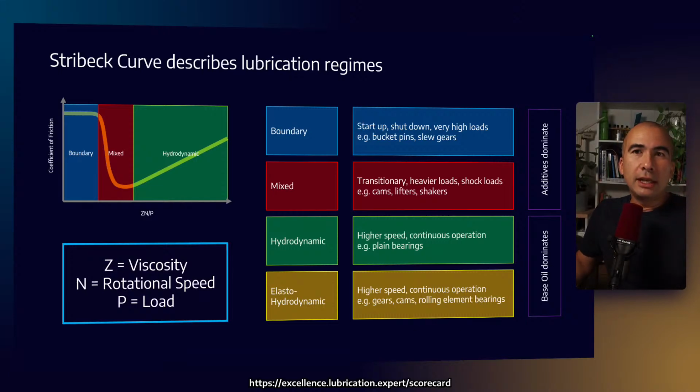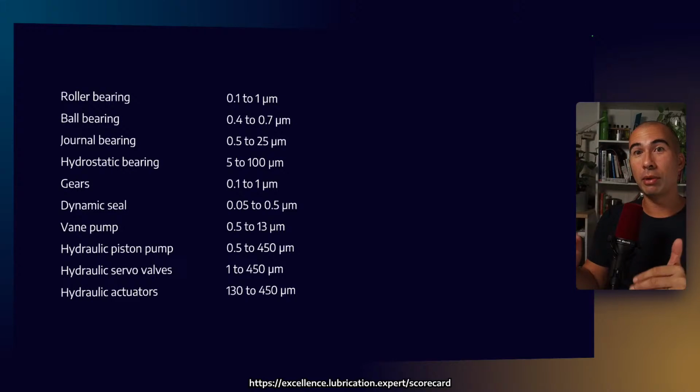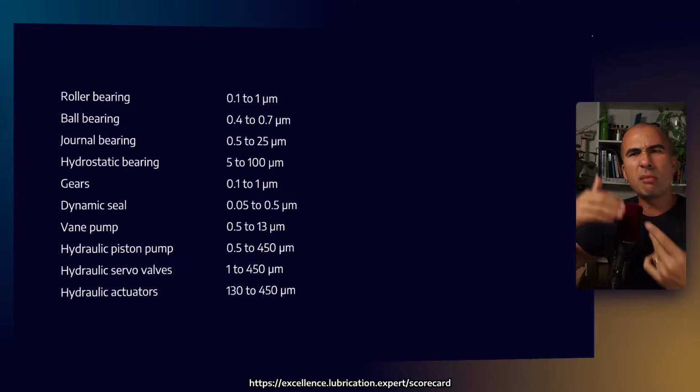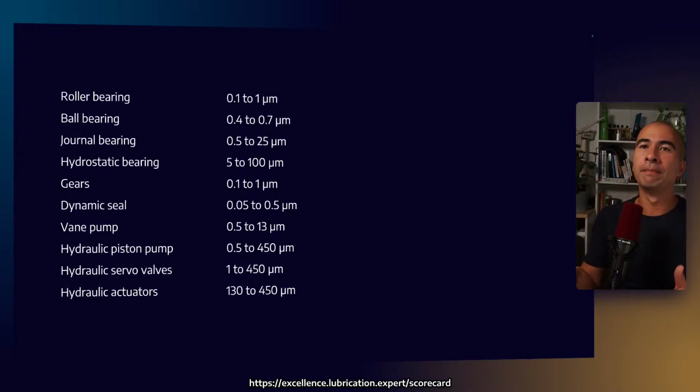Now, if you were going to sit the exam, one of the things you would need to know about the differences between these is that when we have hydrodynamic lubrication, remember that's like a plain bearing, the film thickness is double-digit microns, so 10 microns and above in ballpark terms. If we had elastohydrodynamic lubrication, so that's where we have ball bearings, rolling element bearings, cams or gears, typically it is single-digit microns.